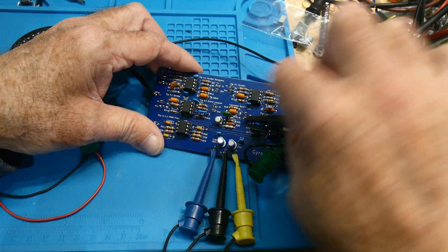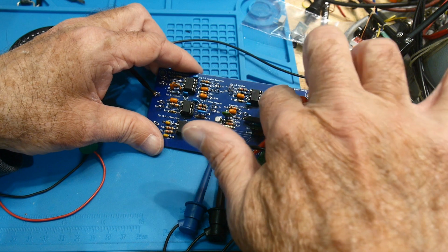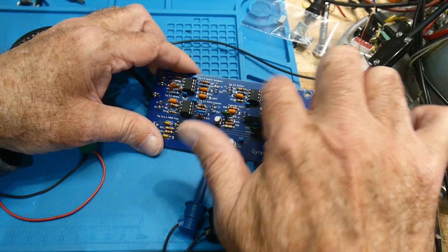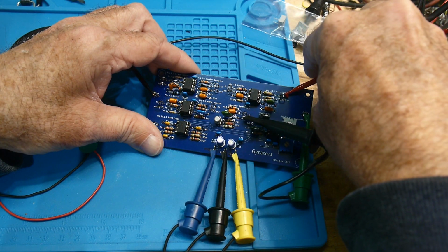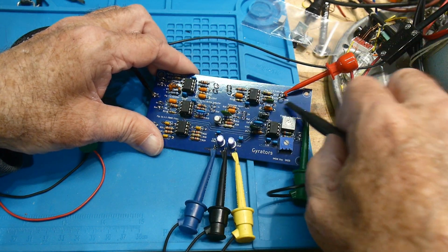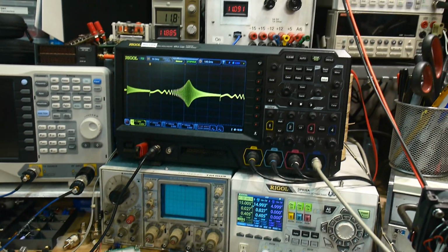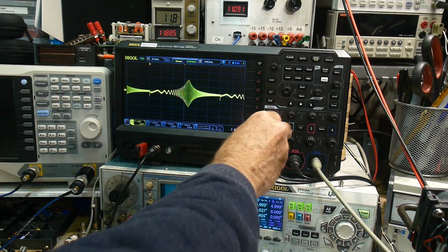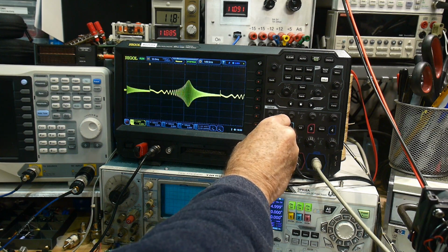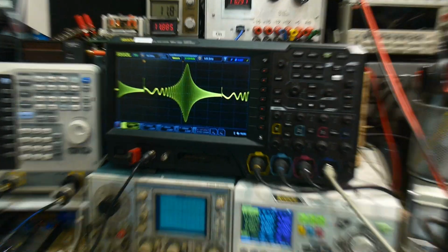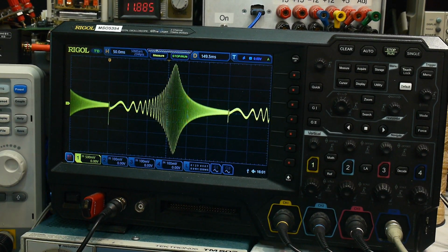Okay, all right, so the two circuits are this one here, which is our op amp version, and this is our transistor version. So let's do the op amp version first, okay? So this is our op amp version. Let's see what it's doing. And oh, it's one of those bandpass ones, okay? So let's make him even bigger here. Okay, so we have this nice bandpass filter made up of a gyrator and a couple of capacitors, all right?